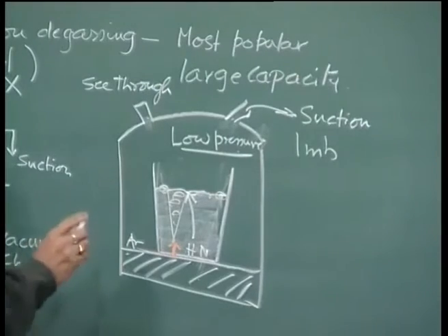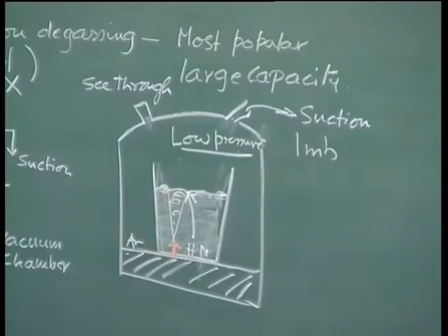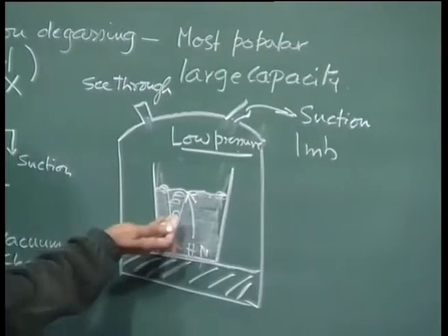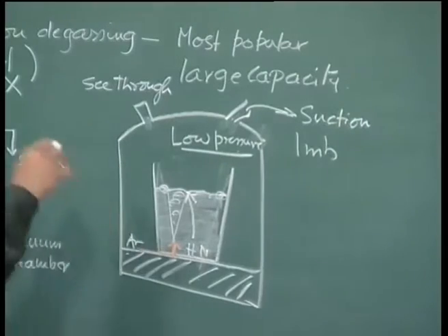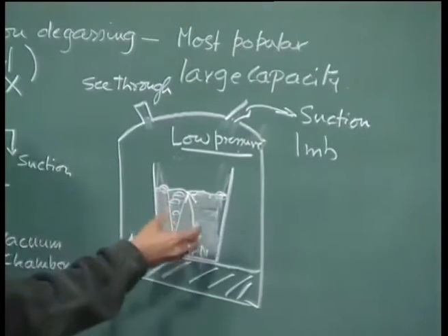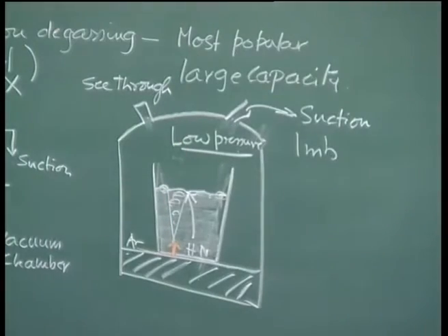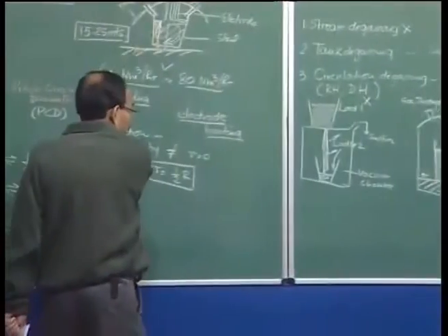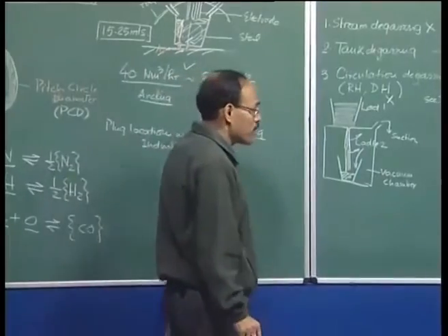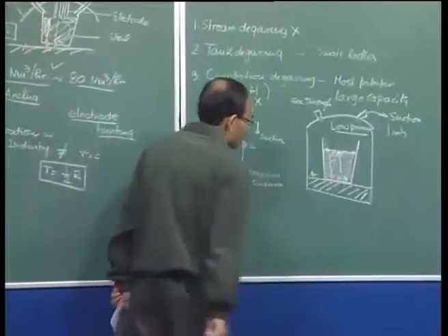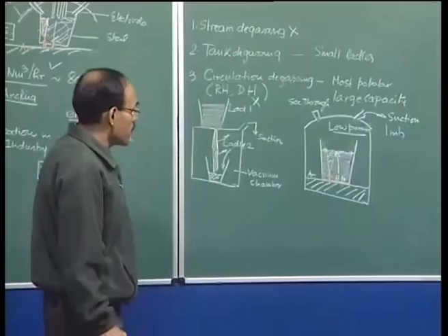So, we understand that the injection of argon gas during the vacuum degassing process is extremely important, as it brings fresh material towards the slag metal interface or the metal ambient interface, and as a result fresh metal containing hydrogen and nitrogen is exposed to vacuum, where these chemical reactions take place, producing ultra low nitrogen and hydrogen steel.